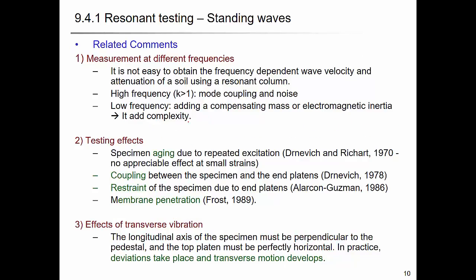And there are several comments and discussions that we can think about regarding the resonance testing. Measurement at different frequencies is not easy, so it is hard to obtain the frequency dependent wave velocity and attenuation. At high frequency, mode coupling and noise make it difficult to get measurements. And at lower frequency, you have a mass, which adds complexity.